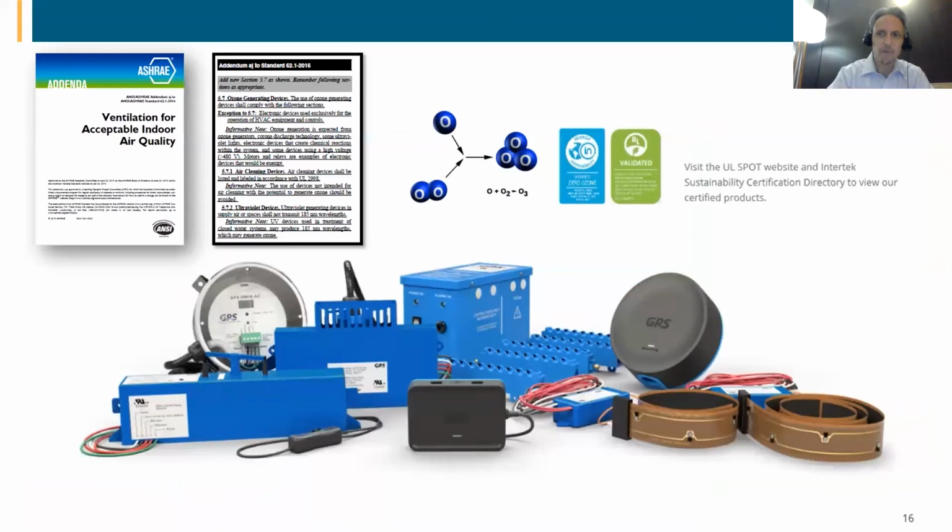One thing that's very important to understand with regards to any type of advanced electronic air cleaning technology is that you want to make sure that product is validated for zero ozone production. Ozone is O3. Ozone is a toxic gas. Ozone is a respiratory irritant. Ozone is something that is created outdoors on sunny, polluted days. We want to leave it outside. We do not want to install any electronics in the building that can produce ozone.